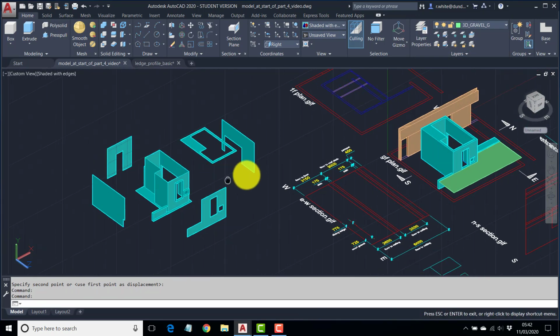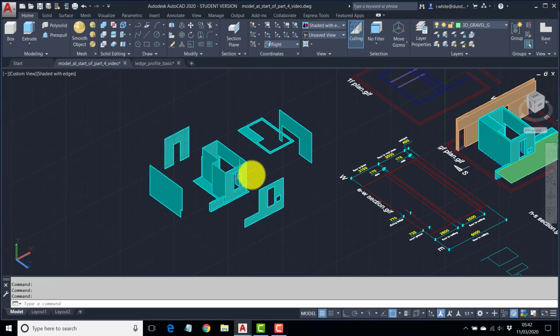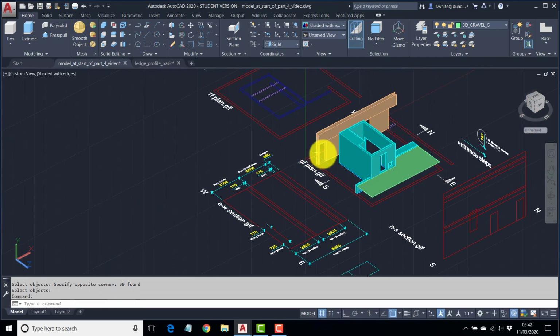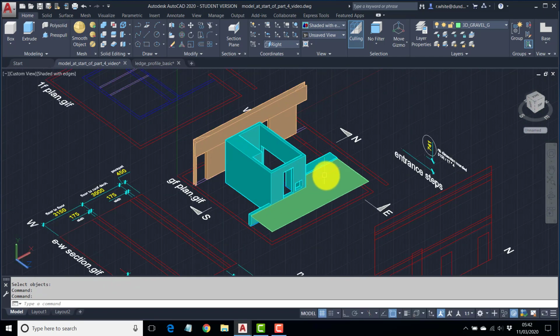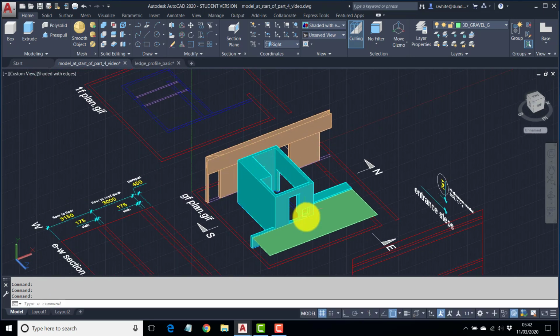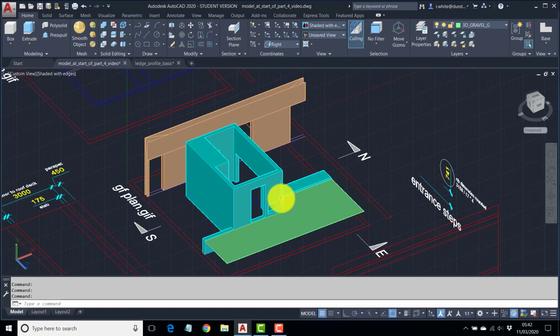Sometimes I use that kind of method, create a solid so that I can actually get hold of the regions. So they're extremely useful for ceilings and floors that have got awkward shapes that you don't want to necessarily 3D face, which is quite laborious. Regioning can be a quicker way to do that, but as with the main solids, they're not quite so editable.